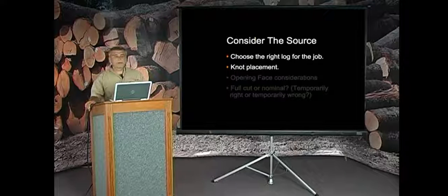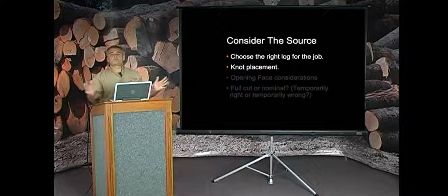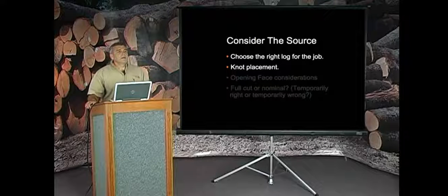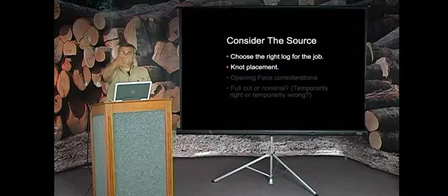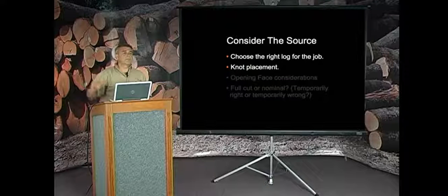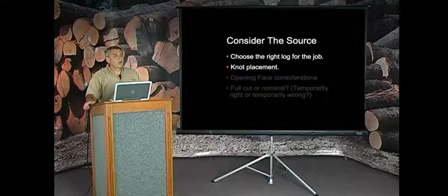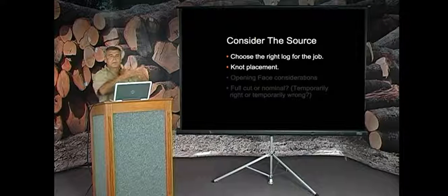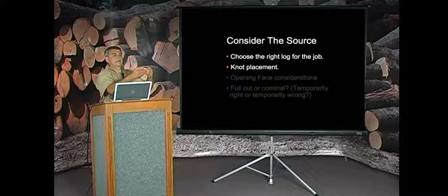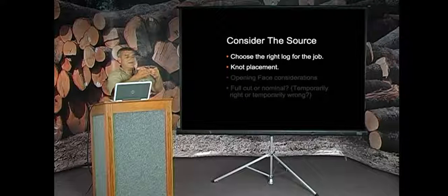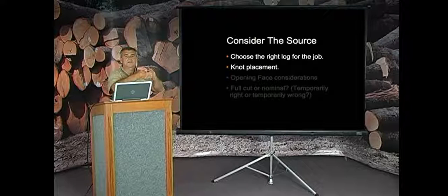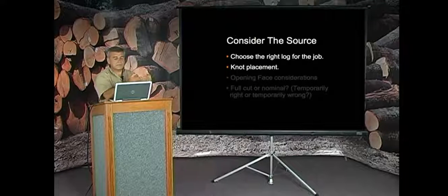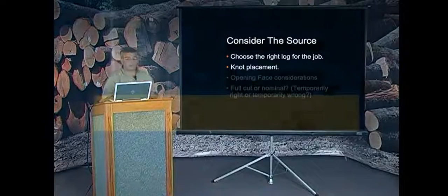When a structural member is called on to span, let's say it's going to be a floor that's 14 feet wide, and we're calling on those structural members to hold that floor up. Well, when that member is put under load and it wants to break, it has to compress the top and tension the bottom of that piece. So knot placement becomes very critical.